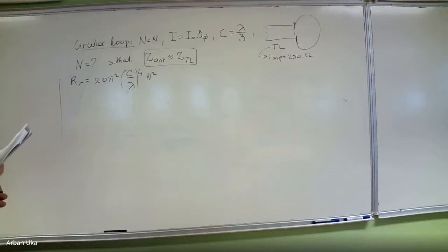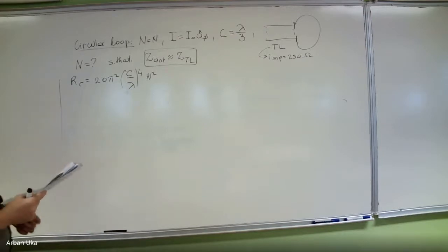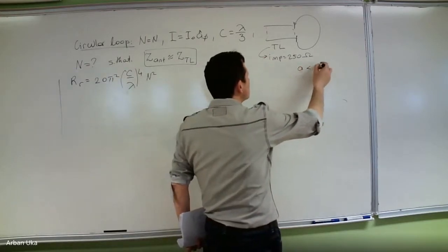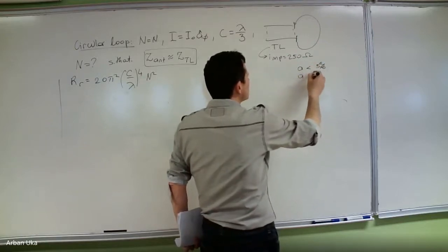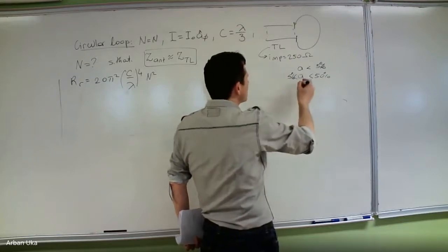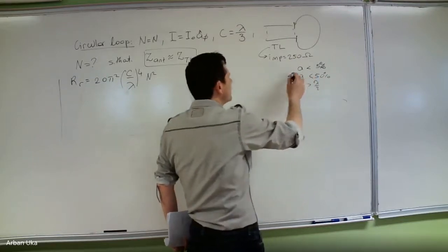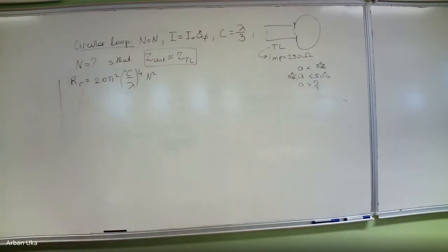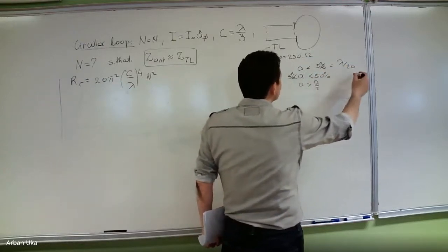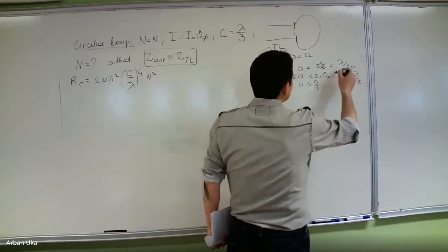Okay, so this is our construct. By the way, we can also have a look at the values we said we had. Whenever A is smaller than 5%, we had one case, and another case when A was larger than 5% up to 50%. There was also a case when A was larger than lambda over 2. So these were 4 different regimes that can be considered for the antennas. When you say 5%, often in the book it is written as lambda divided by 20. Here this is lambda divided by 2, and here A is lambda divided by something else.